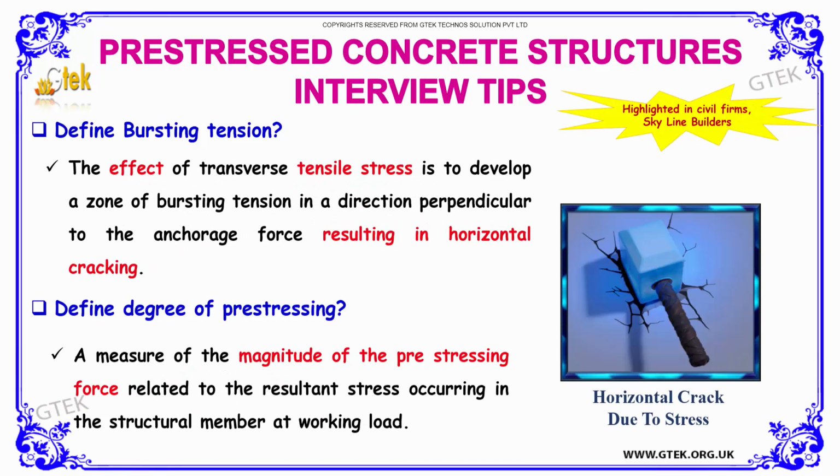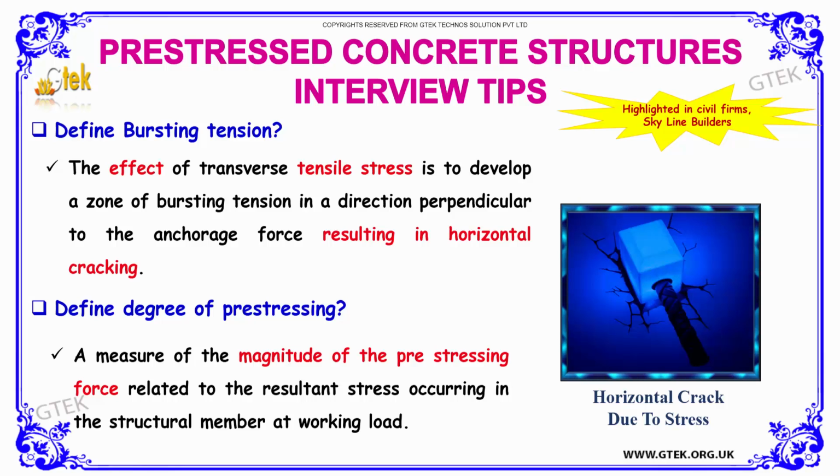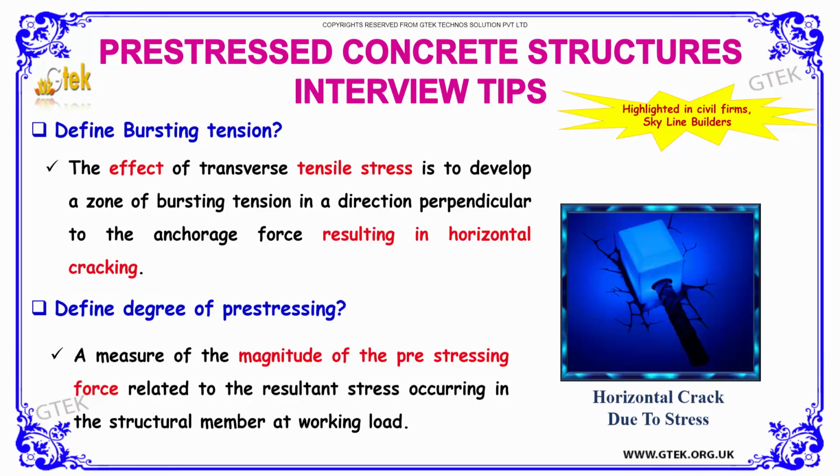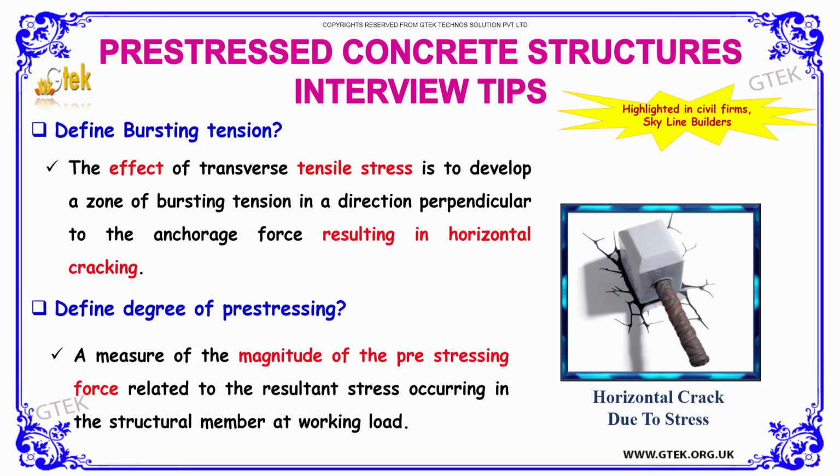We'll move to the next question. Define bursting tension. The effect of transverse tensile stress is developed in a zone of bursting tension in a direction perpendicular to the anchorage force, resulting in horizontal cracking. So this is all about the term called bursting tension.